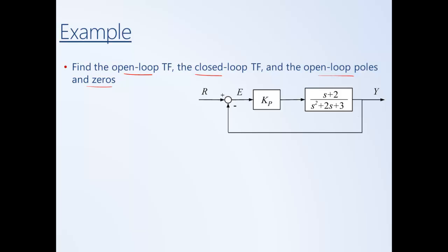So this concept of an open loop transfer function isn't something that we've addressed in great detail, and this might be a little bit confusing, but when I say open loop transfer function, you can think of what we've called previously just the loop transfer function. So when we find the closed loop transfer function of a negative feedback system and we use the form forward over 1 plus loop, the loop is the open loop transfer function.